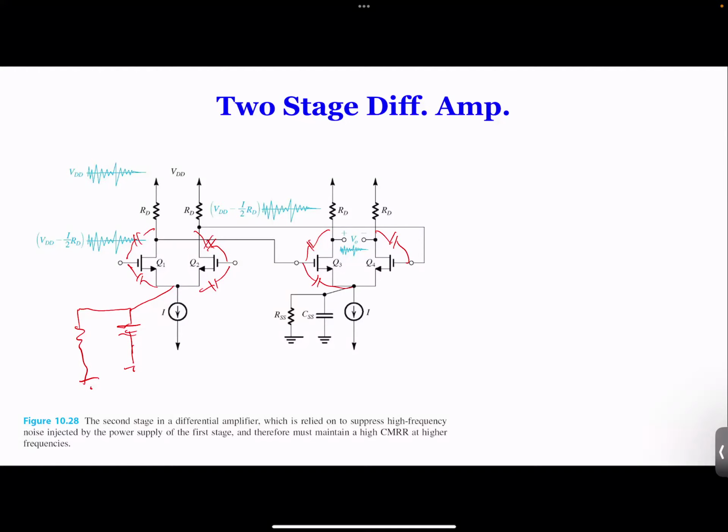Those noises are coming from many sources. Some of those are coming from the power supply itself, for example, 50 hertz, 60 hertz, because you rectify 60 hertz, so that comes in. Some coming from environmental noises, and some like interference from other circuits in the room. Pick it up, that's high frequency. And sometimes, if it's not a linear power supply, you have a switching power supply, and those switching frequencies get picked up. So those are the noises.